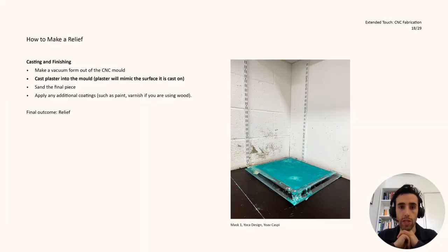The cohort proceeded to the vacuum form workshop where thermal forming was presented as a method for producing lightweight, reusable negative molds with a superior surface finish. A live demonstration illustrated clamp frame operation, dwell time, sag control, and vacuum pressure, translating thermoplastic behavior into actionable fabrication skills. In the following video, the lecturer provided a step-by-step guide on how to use a vacuum form machine.